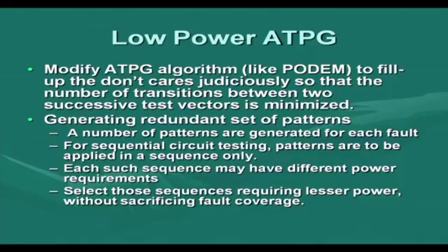So, there is a sequence of patterns that does the test excitation and observation. Each such sequence may have different power requirements. For the same fault I may get different sequences of test patterns, so which sequence we pick up may be an option.